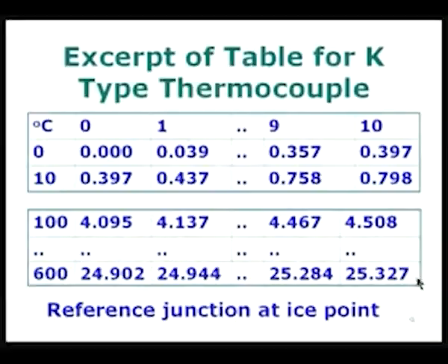These potentiometers, the voltage measuring devices, are available in different ranges, or you may buy one which contains several ranges and use the appropriate range for each range of temperature. If you are measuring between 0 and, let us say, 100 degrees, you put it to the 0 to 5 millivolt range. If it is up to 600, then of course you require up to 25 millivolts, and of course it can go up if you go above.